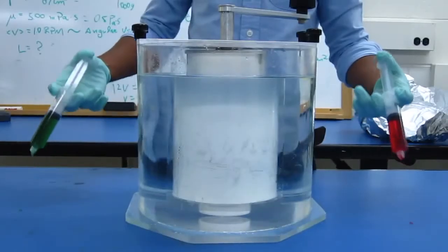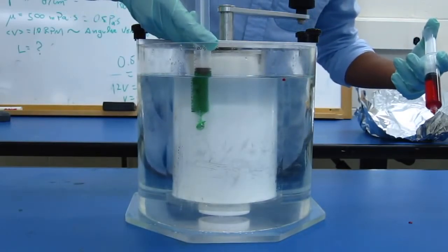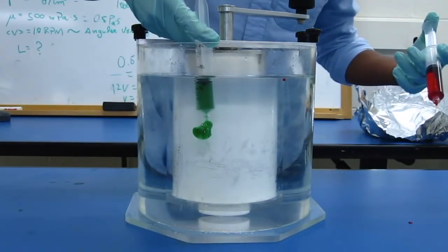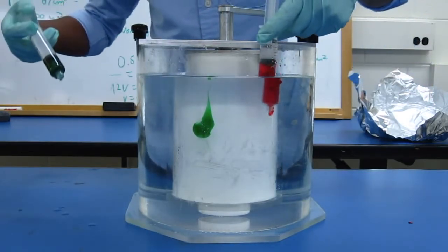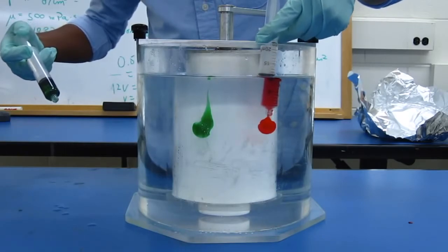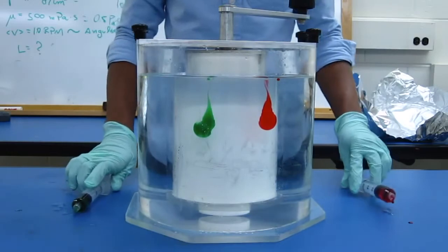One of these things is called Stokes flow. This is the kind of flow that occurs when you have what's called a low Reynolds number, right? And all that you have to know about this is that if your flow is pretty thick, so something along the lines of honey or jelly rather than water or milk, then you'll experience low Reynolds number, right? When you apply a stress to a liquid, you cause it to flow. But when you apply a stress to a liquid with a low Reynolds number, you get a really interesting property.